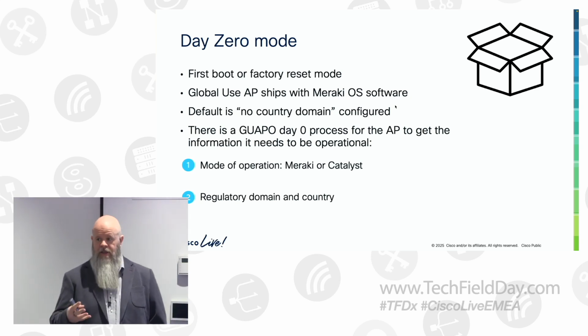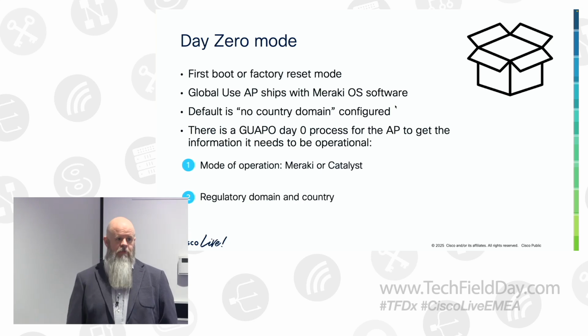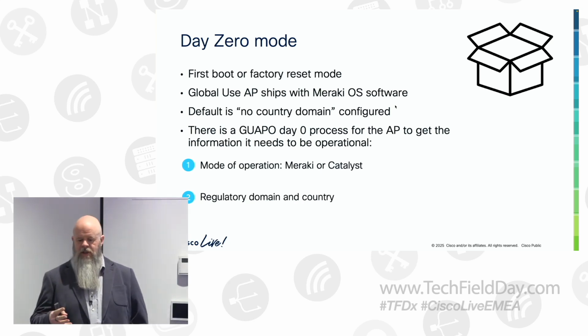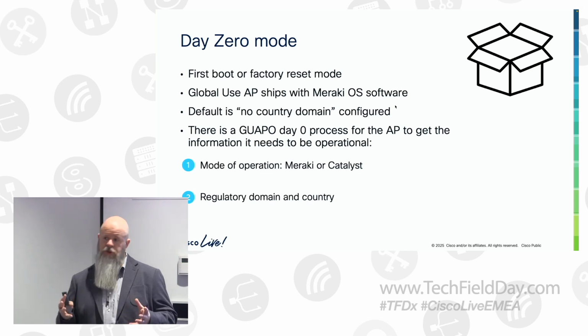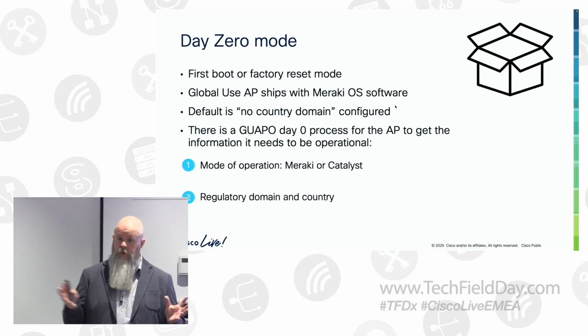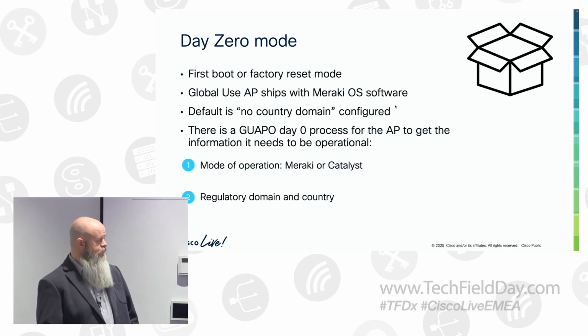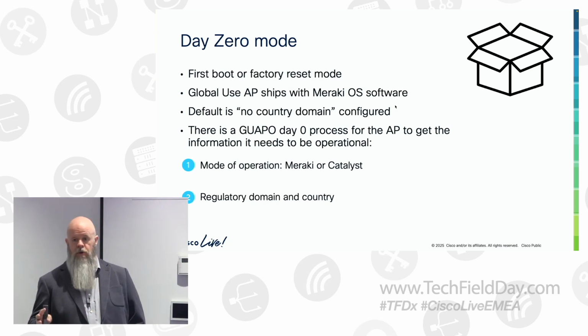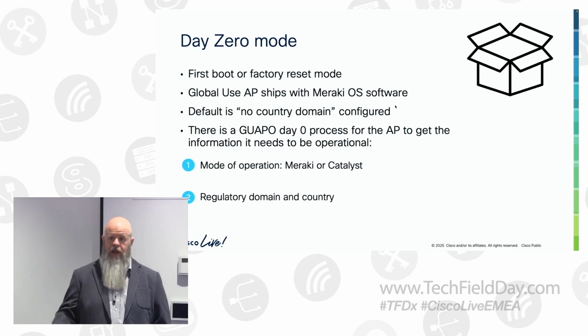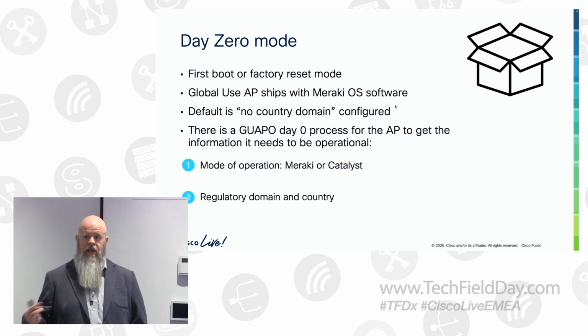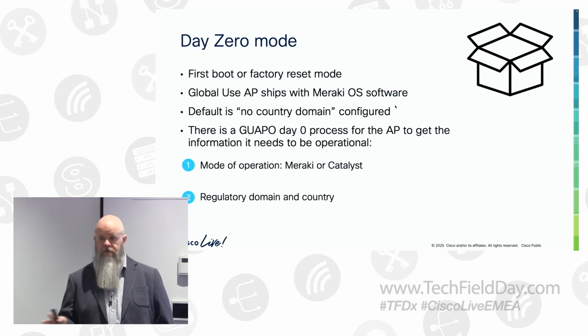What country am I in? What should I be? Am I cloud-based? Am I controller-based? That process takes a little bit of time to go through on the first boot only. Once the first boot is complete, it stays in that mode until you reset it or change it. There's no country code configured by default. It derives that automatically through a number of ways, including GPS and neighboring access points, cloud connectivity, et cetera.